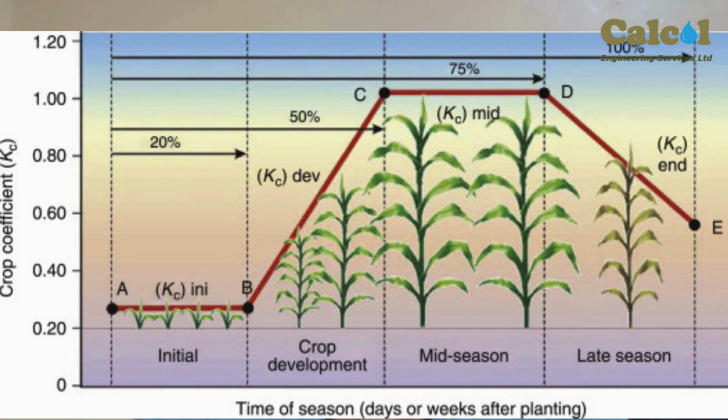Again, if you look at Kc, the climate influences the duration of the total growth period and the various growth stages. So in a cool climate, for example, certain crops will grow slower than in a warm climatic condition. Therefore, to determine the crop factor Kc, it is necessary for each crop to know the total length of the growing season and the length of the various growth stages.